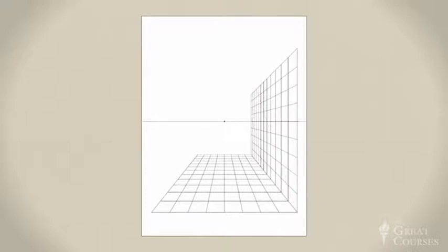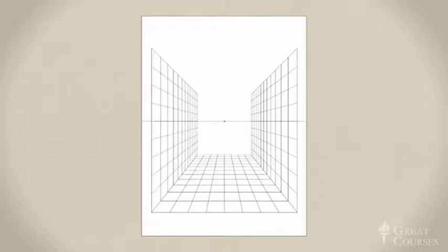Finish this wall and erase any extra construction line. Using your kneaded eraser, adjust the line weights. You want the wall and floor to feel the same at equal depths. If you've been conscientious, it'll get pretty easy now. Follow the same steps to build the left wall. As you're making your way through this, check to make sure that the left side is level with the right.